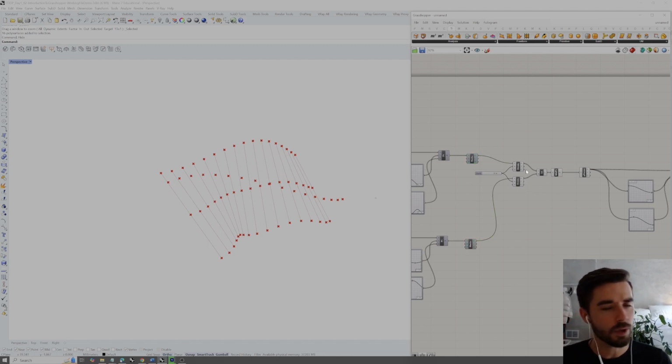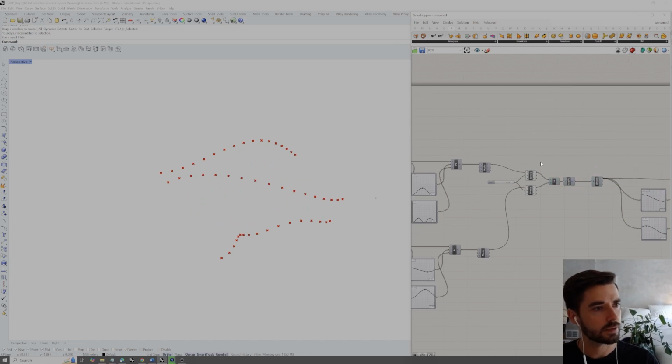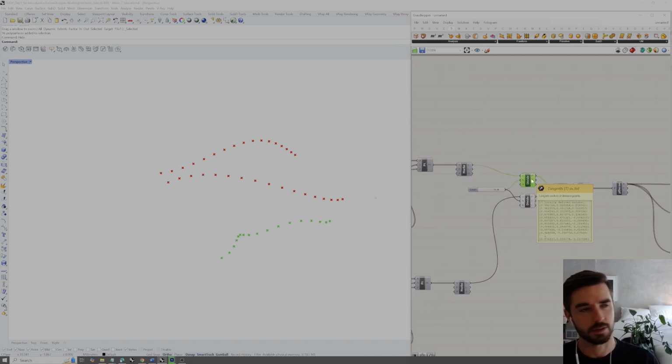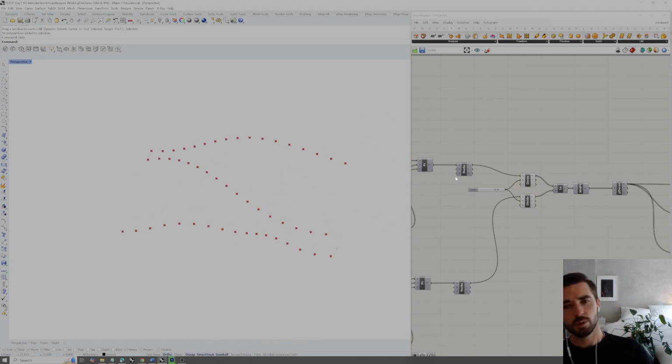We're going to do something a little bit different in this video, which in order to get started, we're actually going to take a look a little bit deeper at these divisions here. So I'm going to hide the preview on everything else, and we're just going to take a look at one of these division sets. So we have 3 of these point sets that we can use to construct a curve because they're a flattened list of points. Now, if instead of drawing a continuous curve through here, we just wanted to go from the first point and just draw one line, just one, from the first point just to the second.